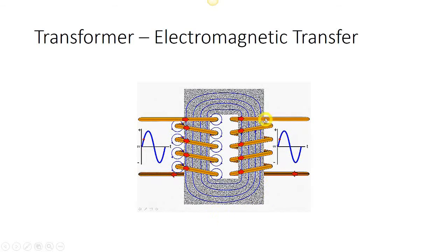And so you see them, they're rotating around here in a counterclockwise fashion, and then when we get to the negative alternation, they're rotating around in the opposite rotation. That magnetic field then, in turn, is expanding and collapsing on this secondary winding, and when it expands and collapses, it produces a current, and that current can then be plotted, current and or voltage.